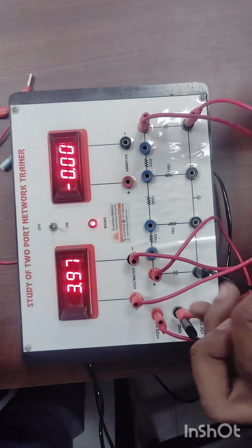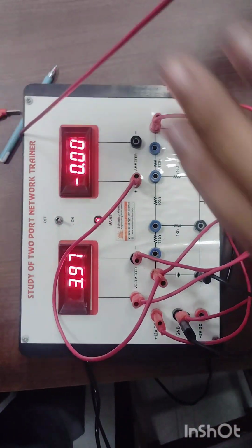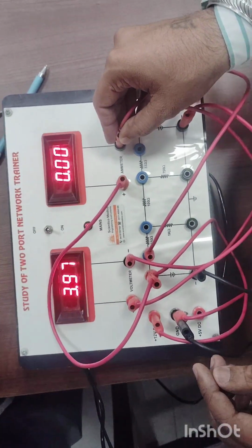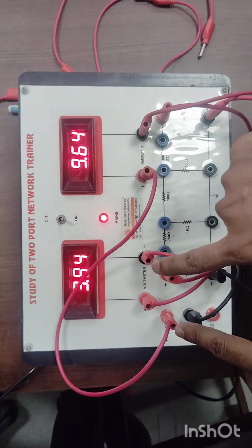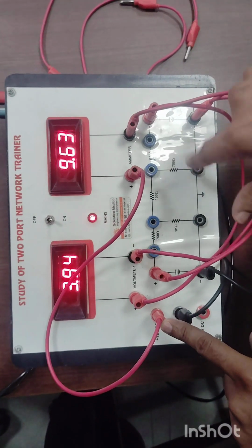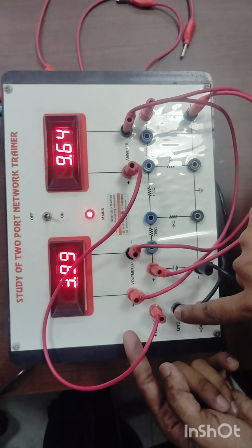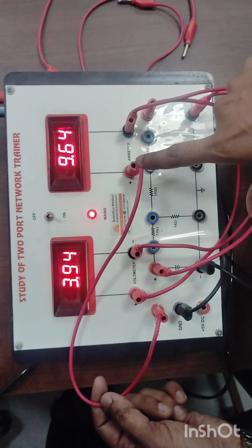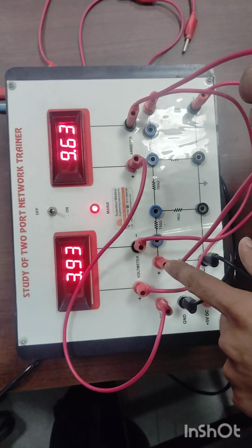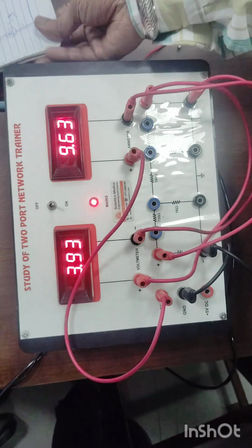This is the first terminal between your power source and network. Here I am going to connect the ammeter like this, because we need to connect the ammeter in series. For measuring I1, we need to insert the ammeter in series between the power source and the circuit. Here you can see we are giving the supply to the circuit through the ammeter. The 12 volt DC supply is directly connected with the ammeter, and the second terminal of the ammeter is connected with the load. So this is your I1.